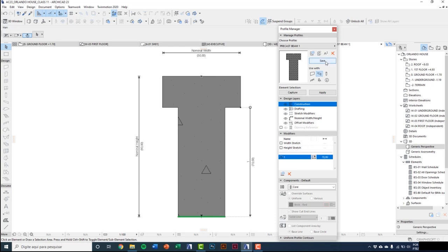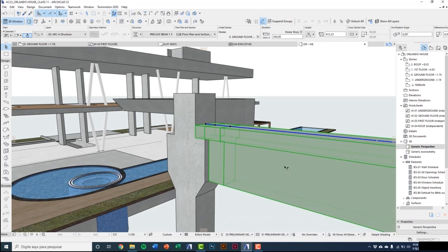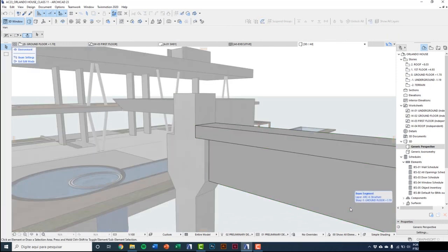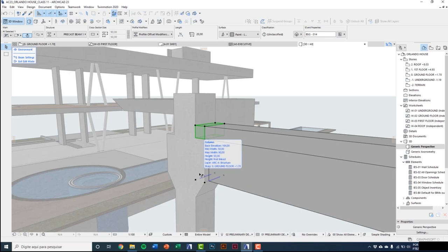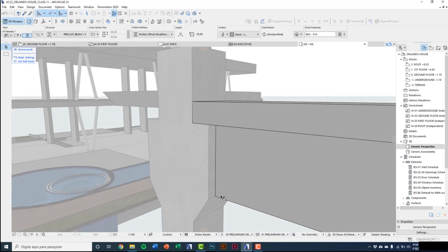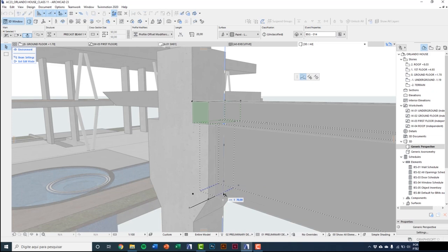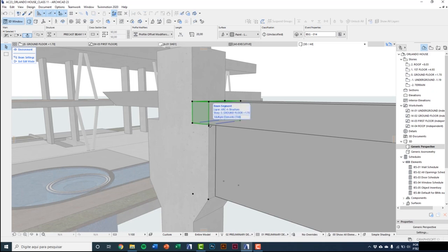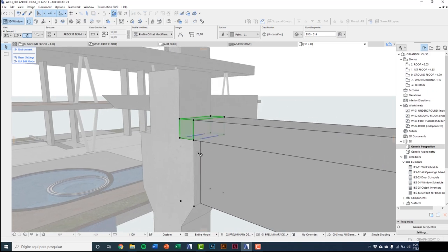I'll save, close the window, select the bin, edit, and selecting the first section, this blue line appears. Clicking on it, using the option Offset Edge, I can elevate this profile. Here in this section, I need more modifiers to do what I want.